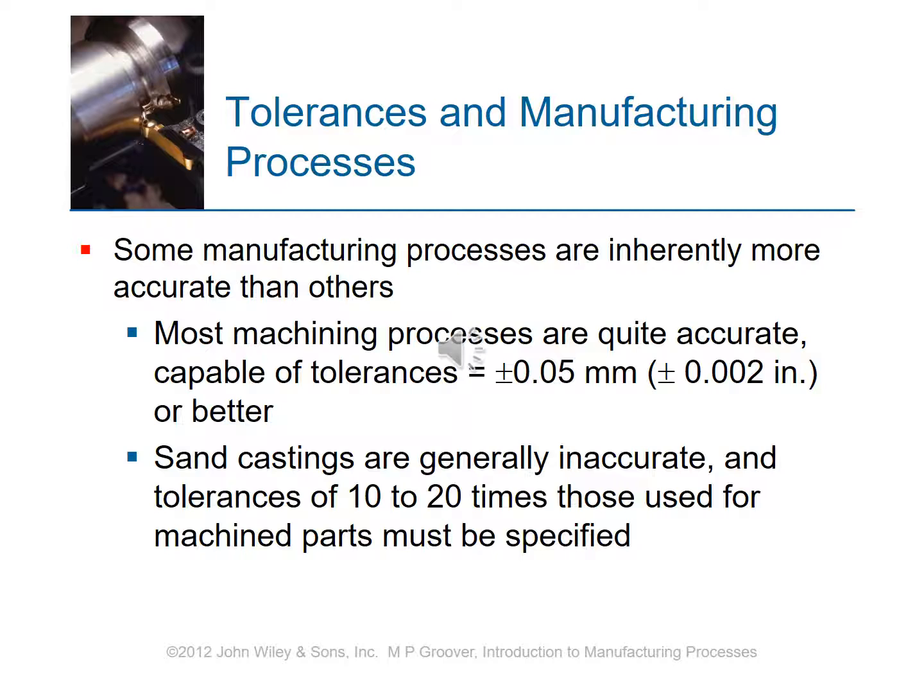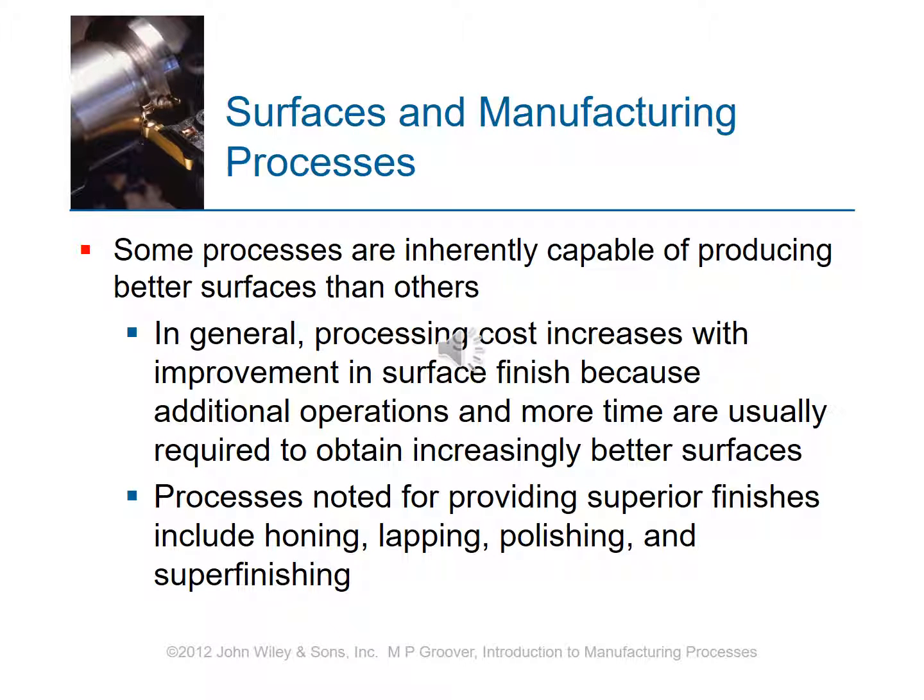It just amazes me how tight the tolerances are that we can hold nowadays. When we were doing hydraulics, we could hold 50 millionths of an inch. You could have some problems with things like sand castings, which need a bigger tolerance, but generally, if you have machine parts, 2/1000ths, or 20/10ths, I'm sorry, it's not hard to do. And they're constantly working on getting better surfaces.